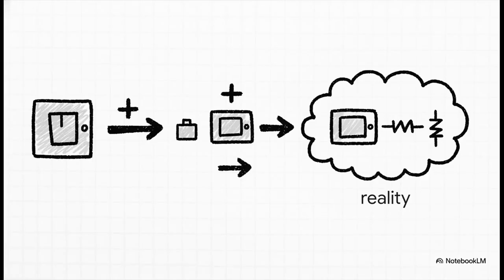So what's the big takeaway from all this? It's really about the power of using models in engineering. We start with a perfectly simple idea, that ideal switch, just so we can understand the main job of the component. Then we strategically add layers of complexity, like that 0.7 volt drop, but only when we need more accuracy to solve a real-world problem.